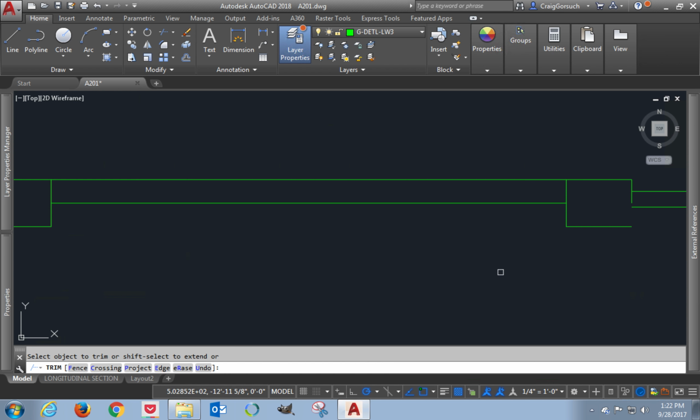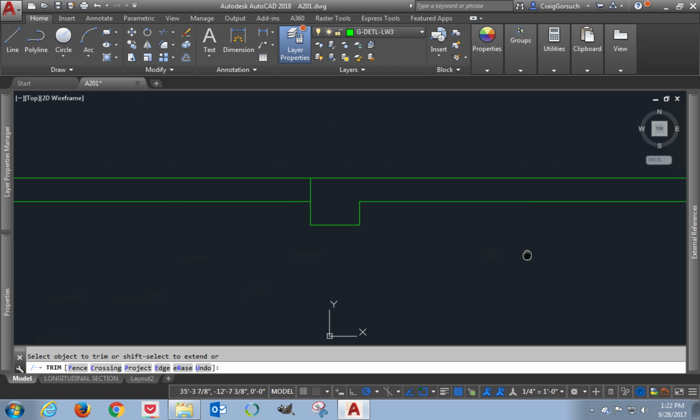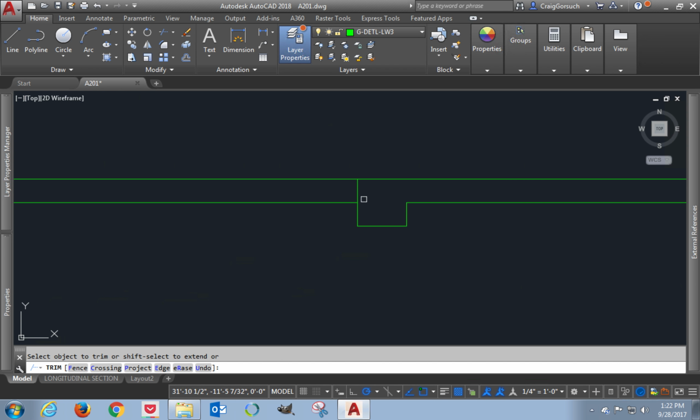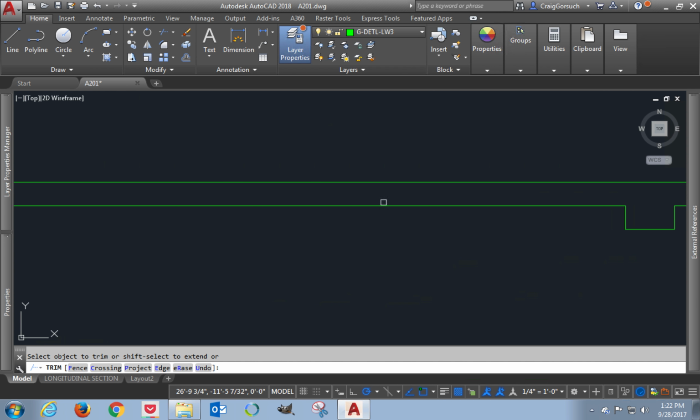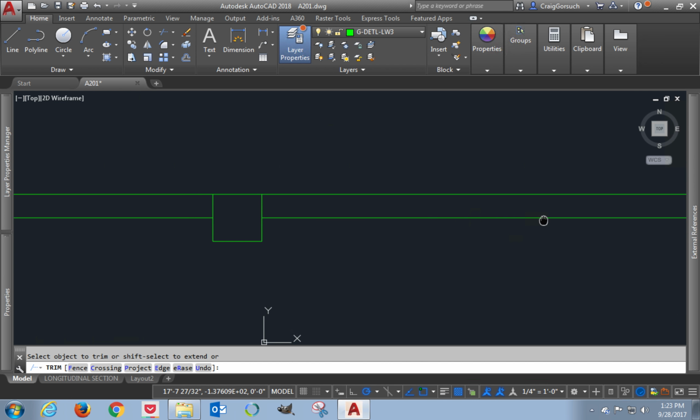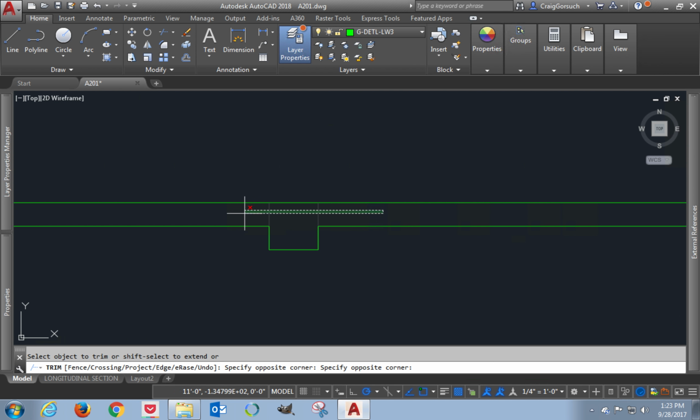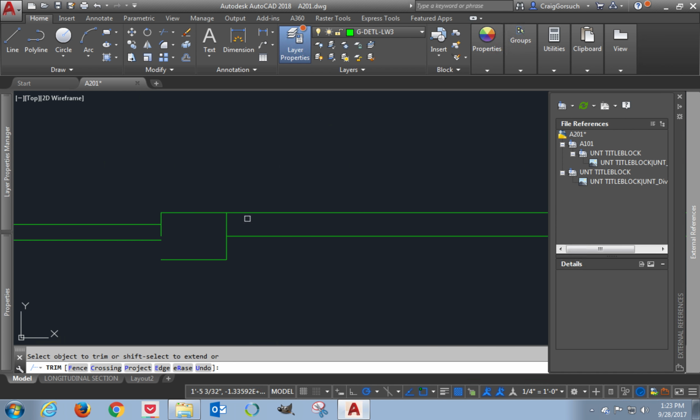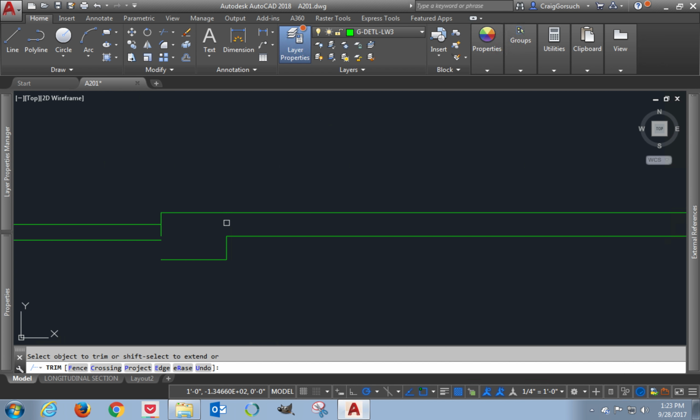Okay, that dynamic thing is making me crazy. I don't like seeing it following me around like this. Okay, I'm going to get rid of those. I'm going to hold my shift key down because that will allow me to extend this little line over here on the side all the way to the bottom like that. Pan over, because I'm still in my trim command. Like that. Pan over some more. I can use my crossing window to get rid of those. Here's another click there, and then hold down my shift key, trim and trim again, or extend and extend again. Okay, I've got those done.